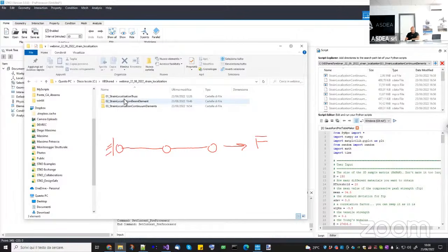Now imagine the cross section is 1, so the force is actually equal to the stress, okay. So divided by the area, which is 1, so it is the same. Okay, so now if any material here shows strain hardening, there is no problem. All the standard rules of finite element work because every material here has a stress-strain relationship which goes always in hardening. If you have here stress and strain, every material point is able to transfer increasing stresses to the next element. Okay, so the deformation will always be smooth along the element. Now, in this case, it will be constant.